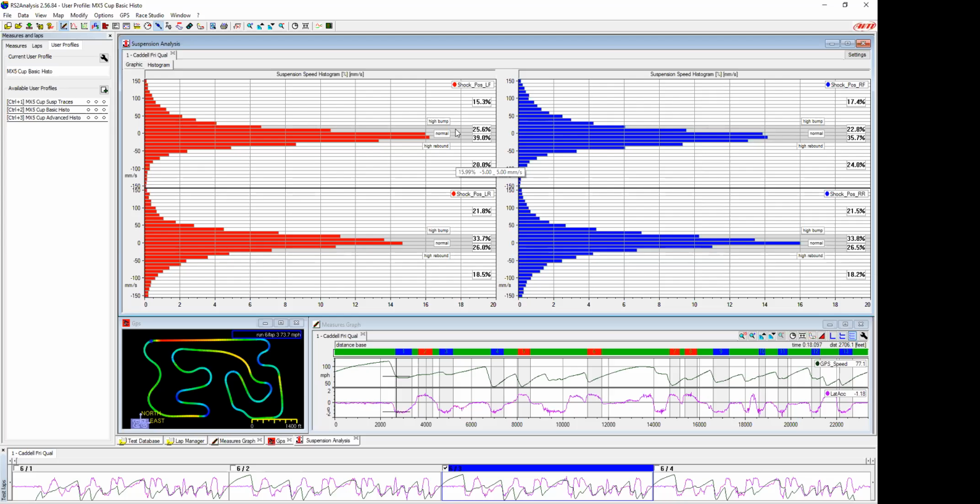But in my case, the shocks that we're looking at here, the low speed adjustment versus the high speed adjustment, happened at 1 inch of speed, right? They're 25.4 millimeters. Anything faster than that ends up being a high speed adjustment, and you take a different adjustment on the shock. The low speed stuff is where the driver has all the feedback, that's what the driver lives in. That's where the driver feels it when he starts to turn the wheel, the chassis starts to roll up, that front wheel comes up, the outer one droops. That is almost all in that low speed adjustment. That's where you tend to work, in this gray area.